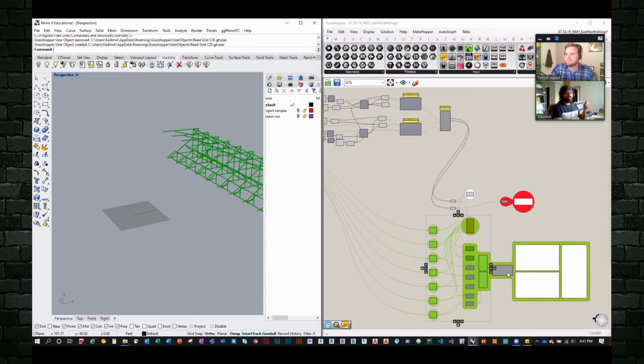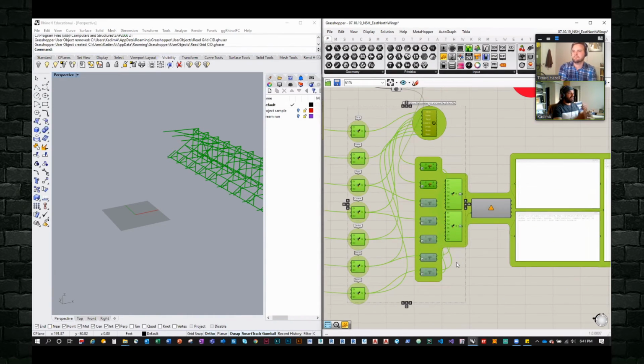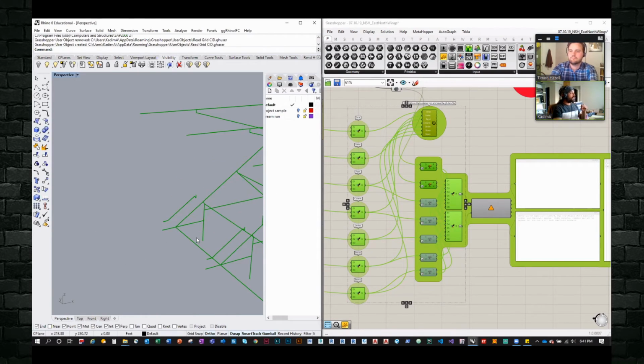So to that point, all this stadium stuff directly translates to Revit. At the end, what this thing outputs is a data set. It's an Excel spreadsheet where each row corresponds to a unique member. So this Raker member has an index, has a section profile, has releases, and so on. And that eventually goes through another script in Revit to build the actual stadium structure.